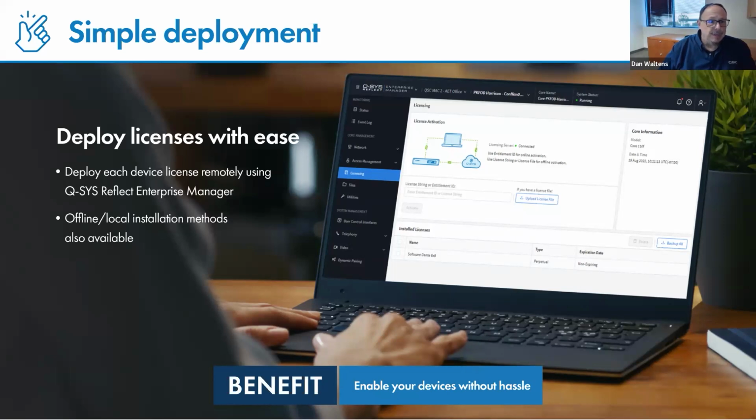And I am using an NV as a decoder with a 4K signal. Can I also use the USB bridge on the same decoder without sacrificing bridging quality? Absolutely. Absolutely, Steve, you can certainly do that. It's not going to affect that. Probably part of the reason we limited it to 750 or 800 megabits is to allow for other traffic on the network. So, all right, well, that gets us back on track.